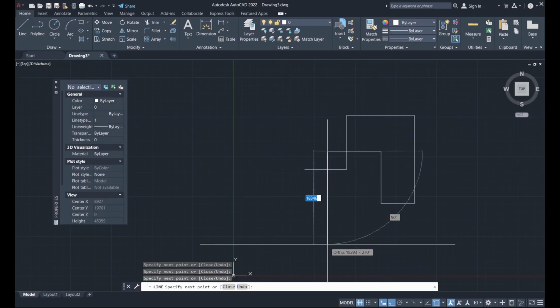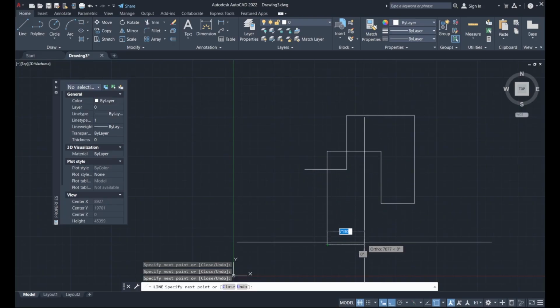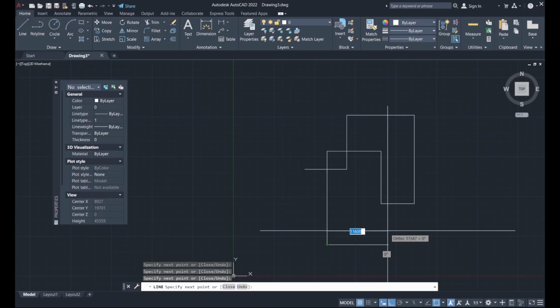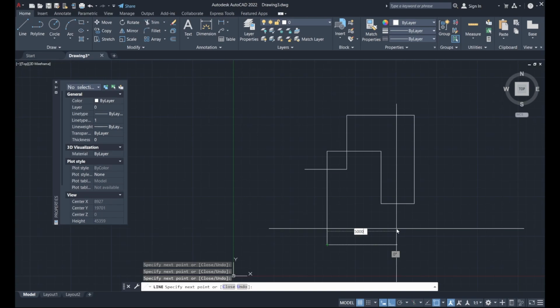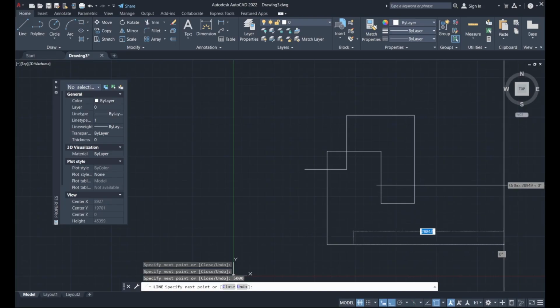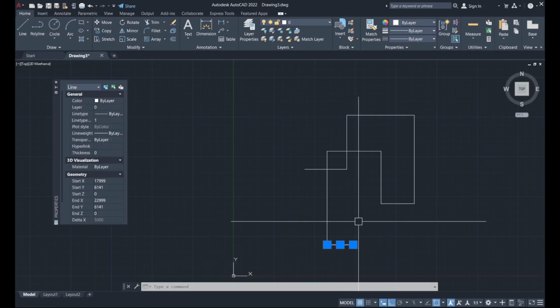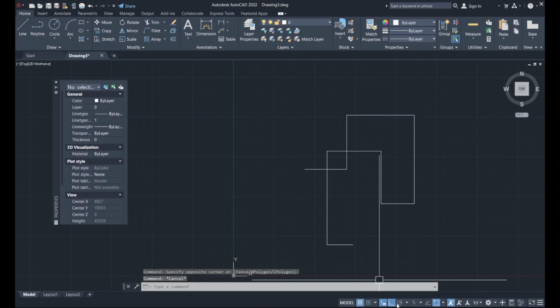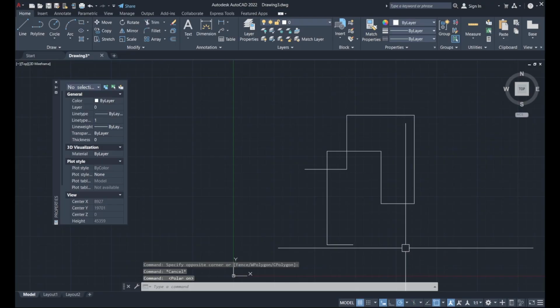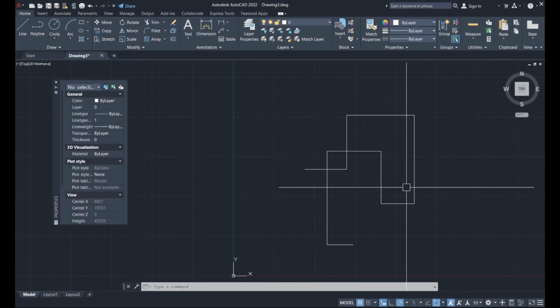Now this is very useful later when you are drawing walls, because it also allows your mouse to just hover and you can just enter a definitive measure of the line and press enter, and now it has drawn your line of that length, which is 5000 units. And just know that when ortho is on, obviously polar tracking will be off, so whenever you select polar tracking, ortho will also turn off. It's one or the other.